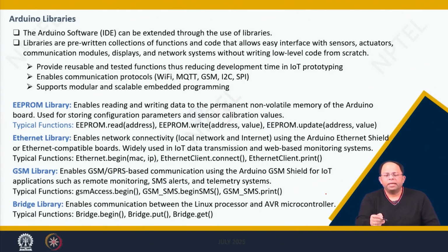So the Arduino IDE is extended through various libraries. Libraries are a pre-written collection of functions and code that allow you easy interface with sensors, actuators, communication modules, displays and network systems, and we don't need to write low level code, so we can just call the ready-made functions and utilize them directly. So this allows reusable and tested functions, thus reducing development time, same as any other libraries, and enables communication protocols like Wi-Fi, MQTT, GSM. So I2C, SPI, all these functions are written. We just need to pick and choose, and then it supports modular and scalable embedded programming as well.